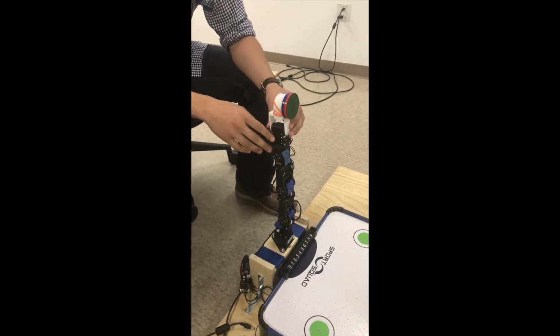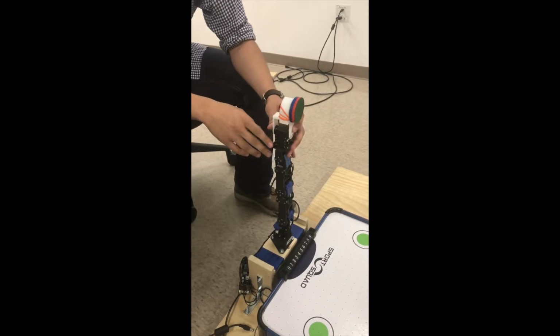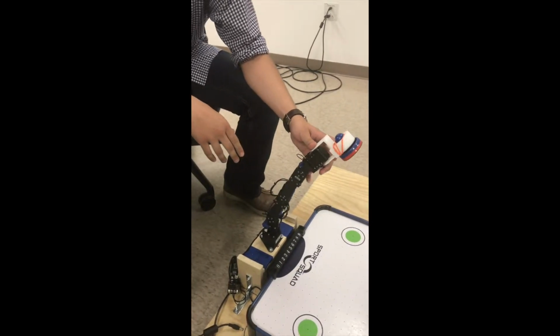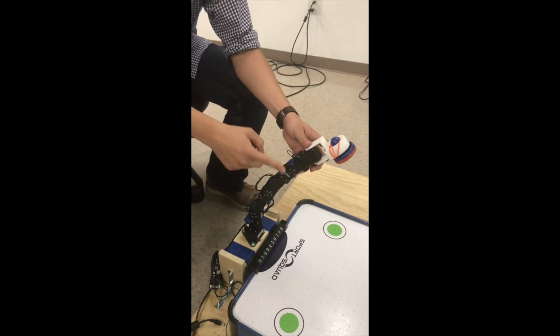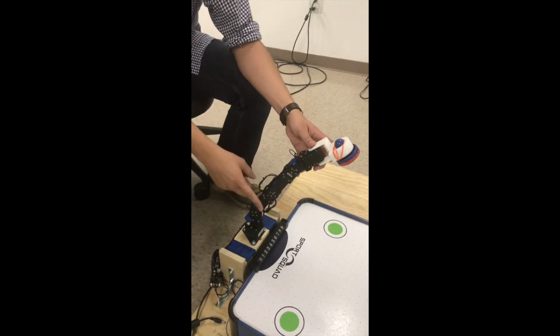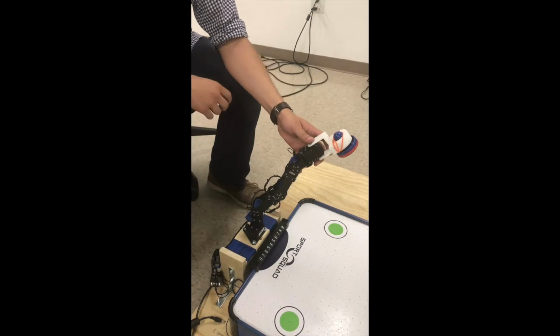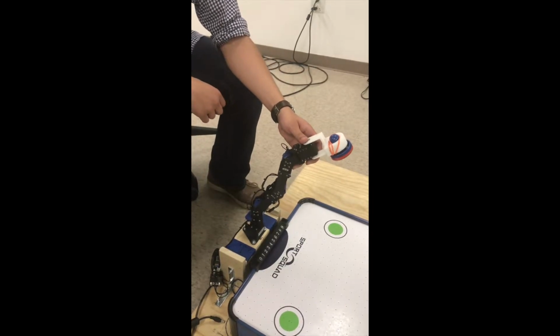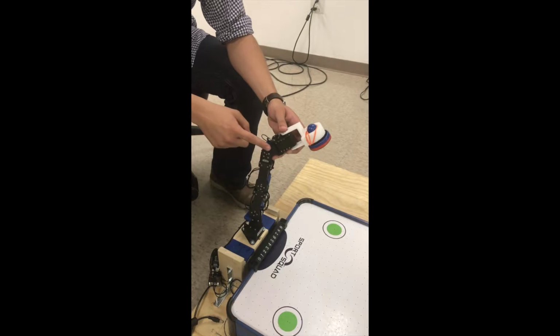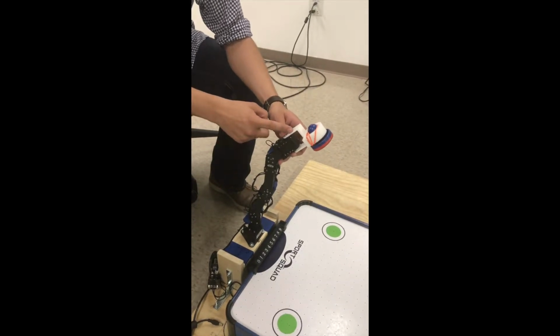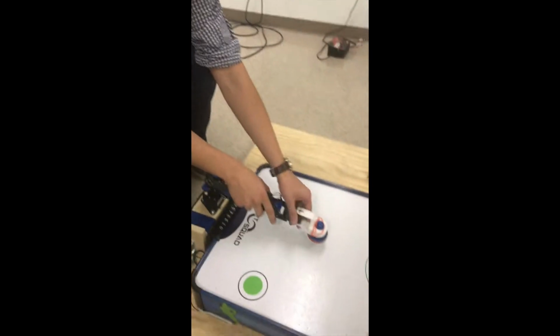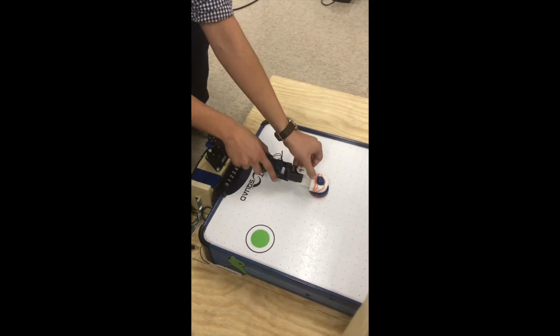The Rex arm is a 4-degree of freedom robotic arm designed in the April lab at the University of Michigan. The Rex arm is composed of several 3D printed links with Dynamixel servos as the joints. The servos help to both control the Rex arm and report its current orientation. At the end of the Rex arm, we 3D printed 2 parts to position the striker and rotate it on the air hockey table.